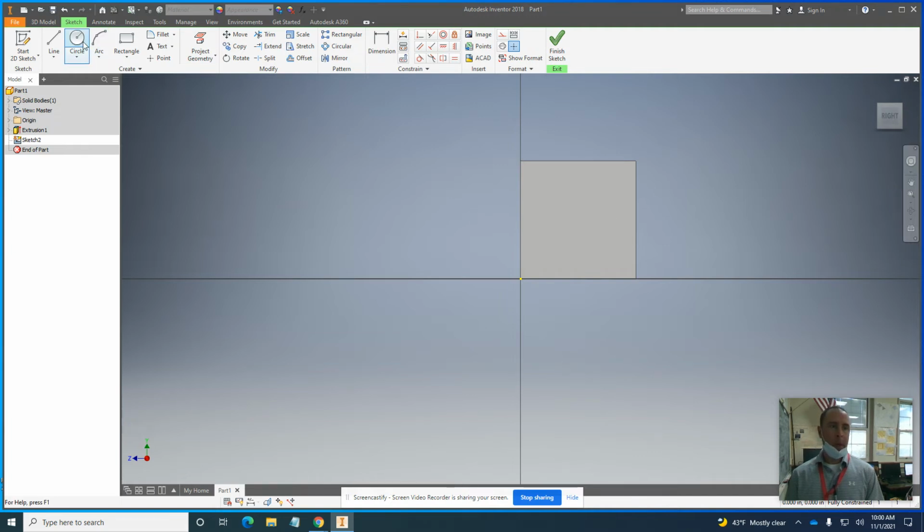So a dice has circles on its sides, and I'm just going to try to put a measurement that looks right. Okay, so right now that circle is close to the center, but I did not give it a dimension yet. And I think we'll make it nice and simple. 0.2, 2/10 of an inch. Looks about right. And now I want to measure from the side and the top to make sure that that circle is in the center.